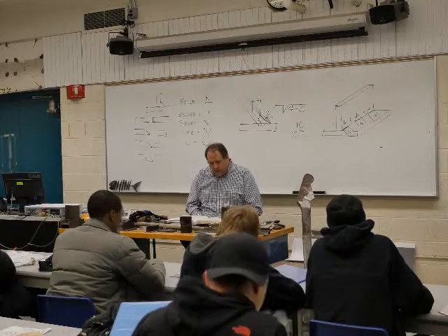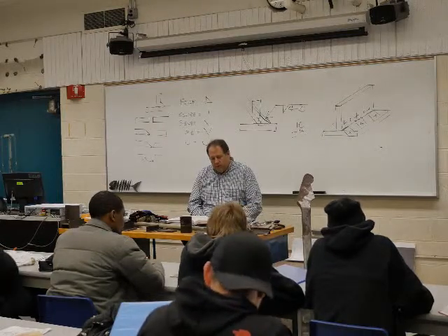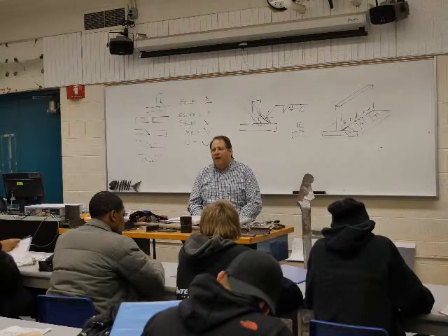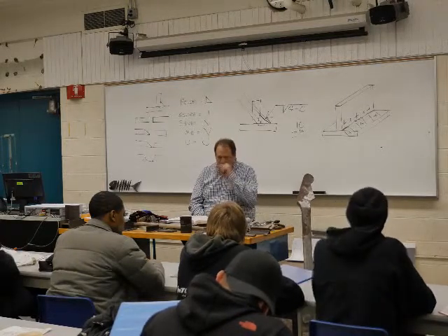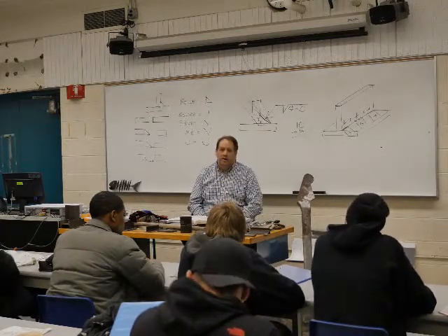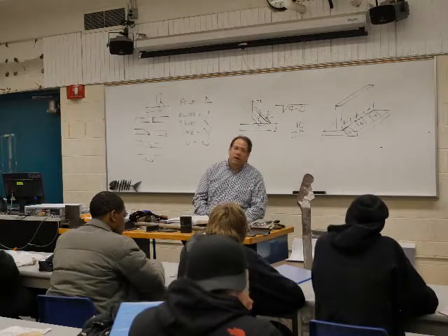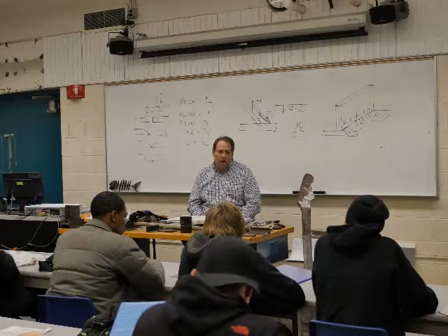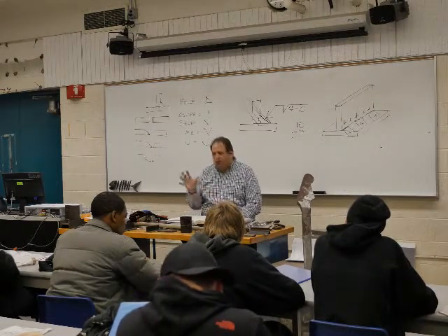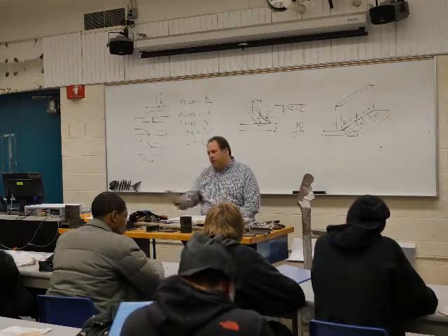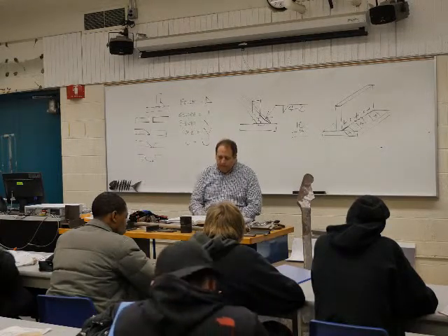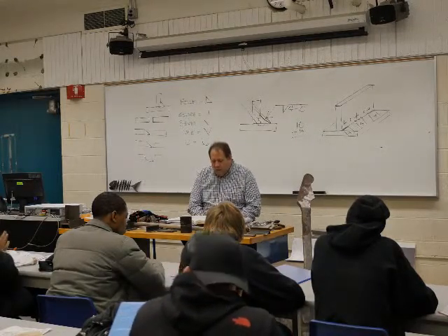The other one is depth of penetration, size, or strength for certain welds. Sure, but again, that is not something that when you weld a piece up, most people are going and then cutting and then etching and then looking at the penetration and then testing for strength. In a normal situation, that doesn't happen except by a welding inspector or by an engineer or something like that.